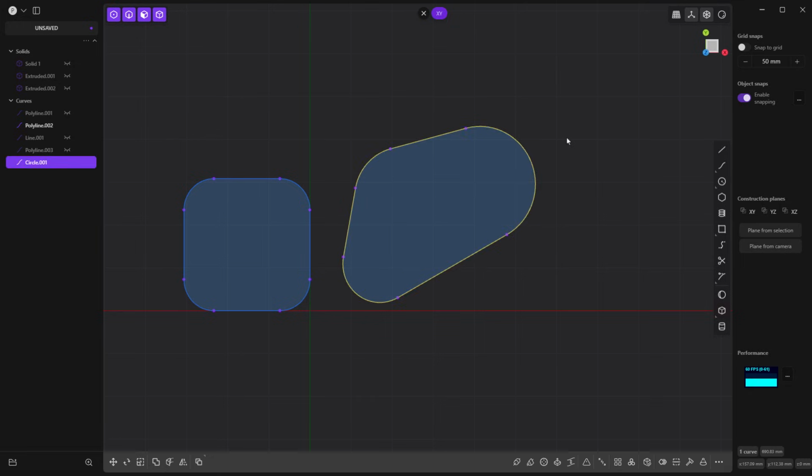It's all considered one polyline. That's taken on the name circle because that was the first object in that selection, but it is a grouping of lines and arcs to create our closed profile. So that is important as those are the default snaps. But there are some other snaps that we can get to by using the shift key.